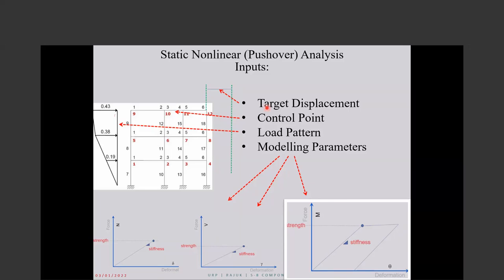For the performance-based codes, for the evaluation of existing buildings, we usually check the plastic deformation of the elements, the deformation control actions. So the story will have three endings. Either you push the building and this building can't reach the target displacement.